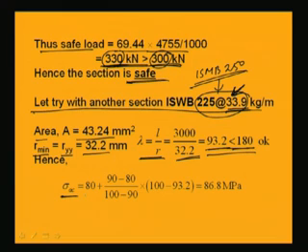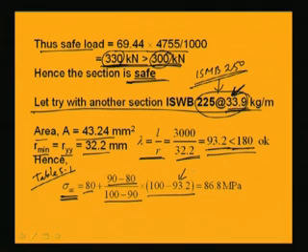Now, what we will do, the allowable sigma SE from table 5.1. From table 5.1 I can find out the allowable sigma SE value is coming 80 plus 90 minus 80 by 100 minus 90 into 100 minus 93.2, because we have to find out the sigma SE value at 93.2. So, this we are getting 86.8 MPa.